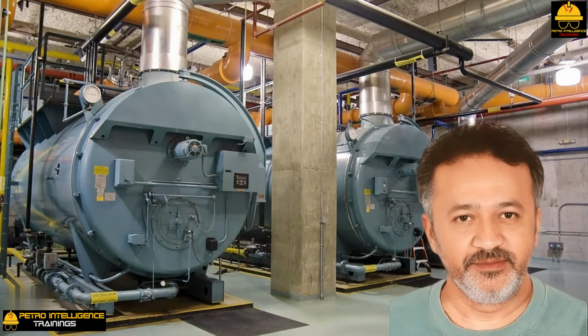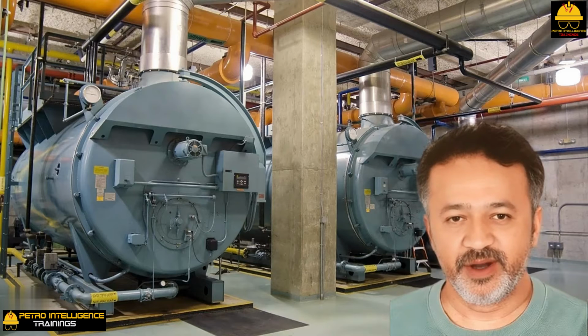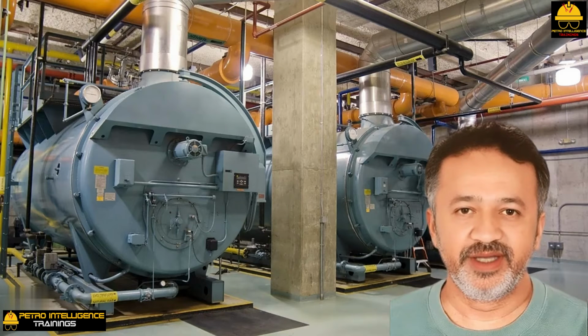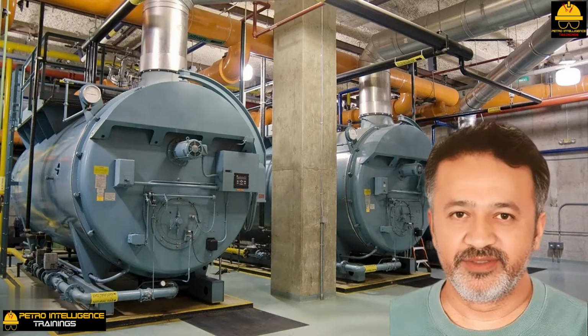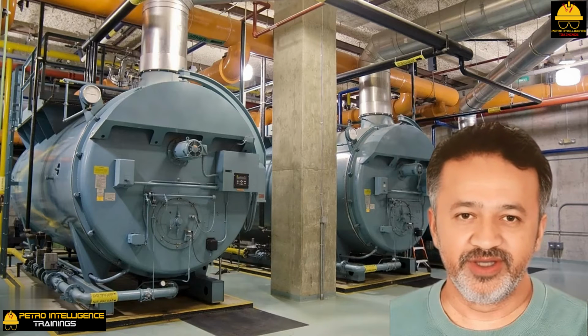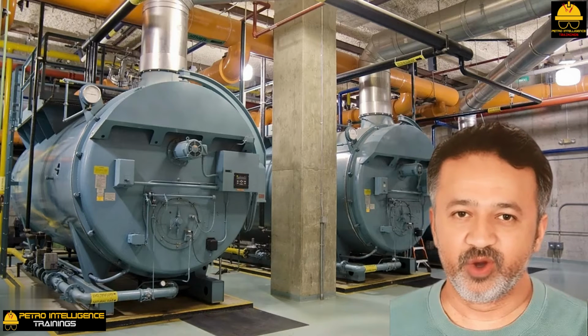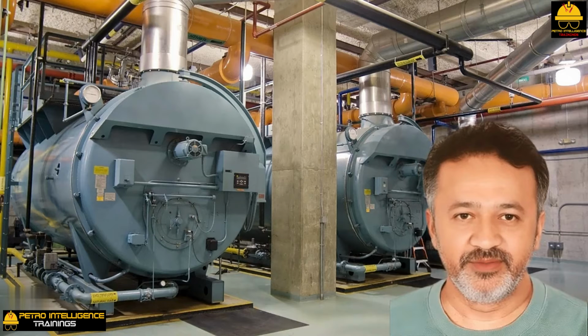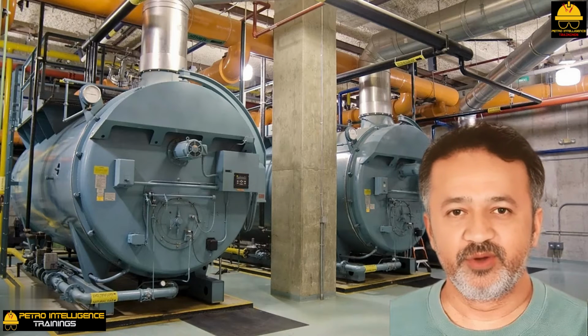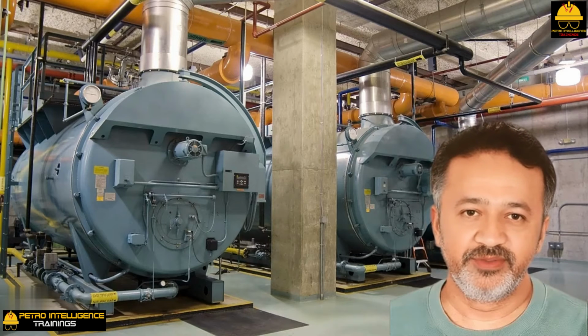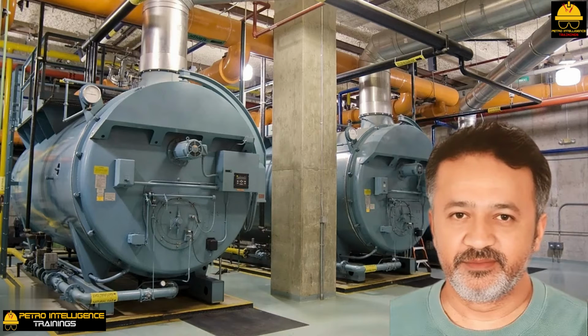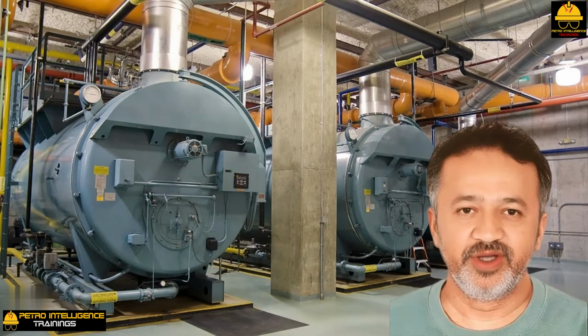Superheating steam. One supplier had some very bad experiences with superheating steam furnace convective tube failures. The cause of tube failure was overheating of the tubes due to hardness deposits precipitated from poor quality steam. The convective section tubes will typically be carbon steel, which fails at about 1000 degrees Fahrenheit. The one case I have in mind occurred at a large refinery in northern Spain.